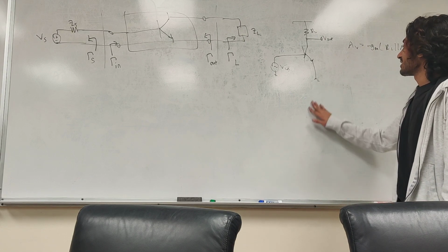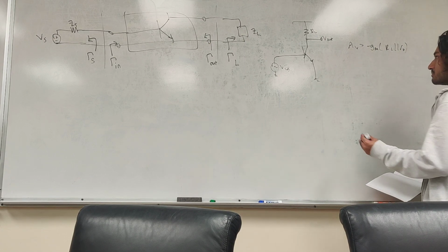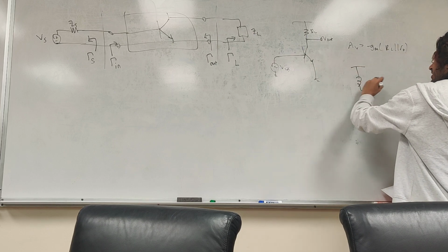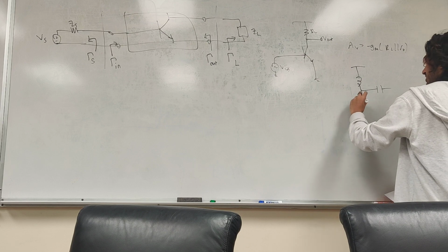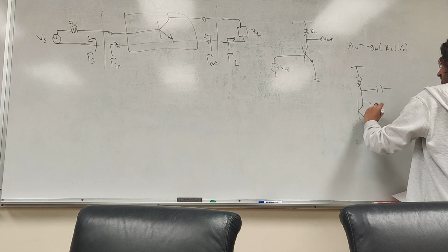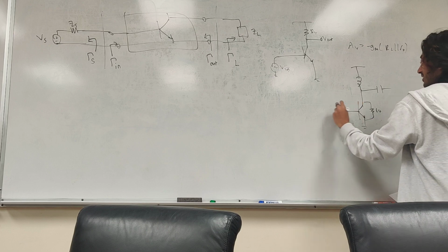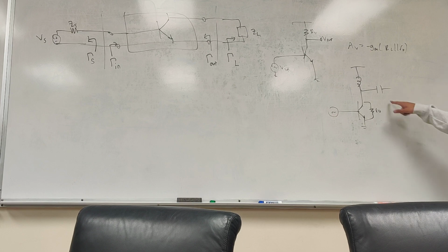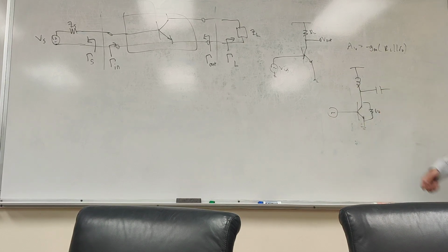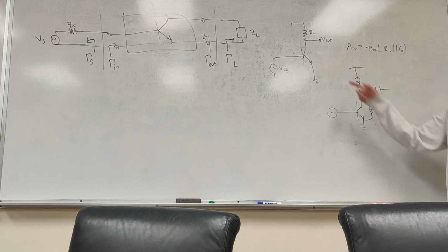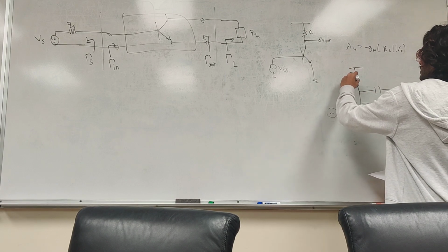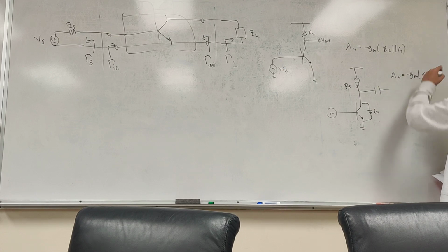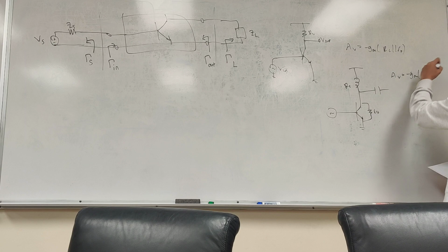However, we still end up having, we think about that, right? What we did before, we said, okay, there's going to be an inductor here, and there's going to be a capacitor, and then that's our BJT. This has some ro. So it's ground, so voltage source, our input. Our gain is going to be negative gm ro, assuming this resonates with this and looks like an open. In reality, this is going to have some parasitic resistance. So RS. So our gain now is still negative gm ro in parallel with some resistance. It's not RC anymore, it's RS.